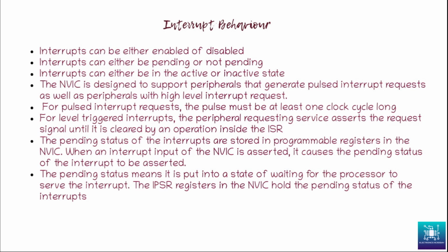Now the pending status of the interrupts is stored in programmable registers in the NVIC. We saw the exact registers which actually store the pending status of the interrupts. The pending status means it is put to a state of waiting for the processor to serve the interrupt. So the registers in the NVIC hold the pending status of the interrupts, as we saw just now. Okay.